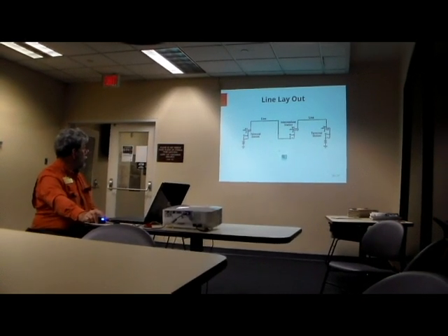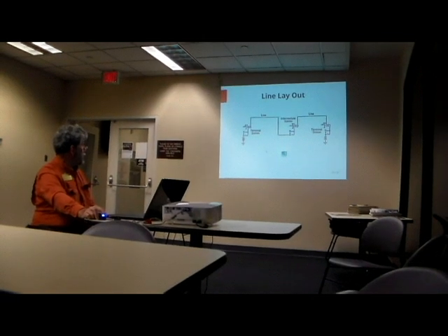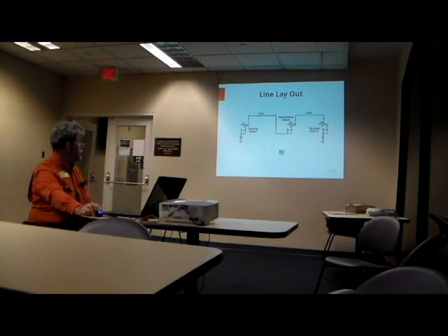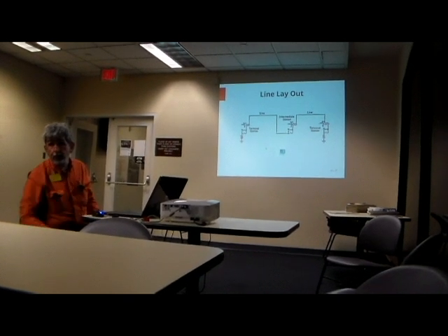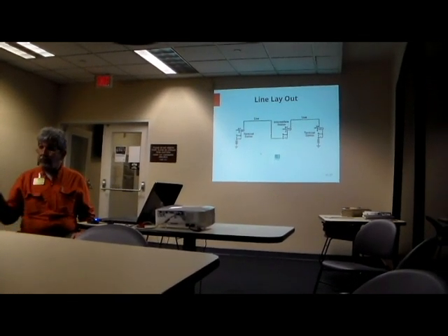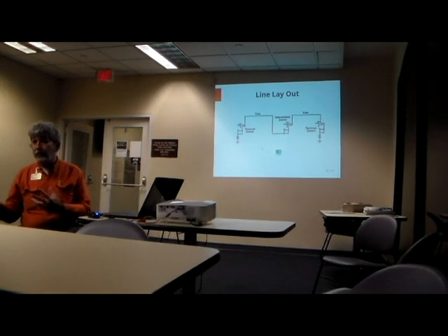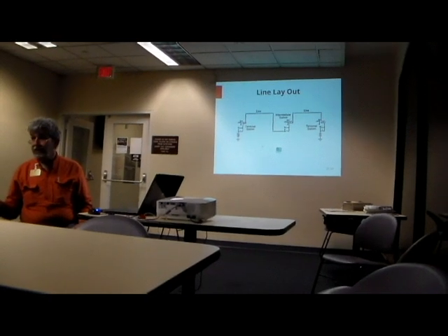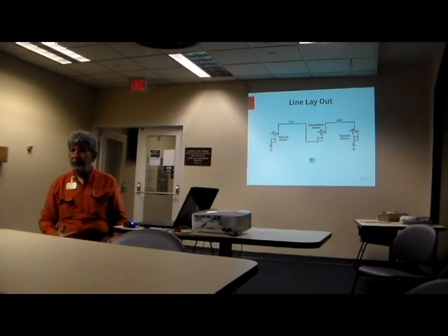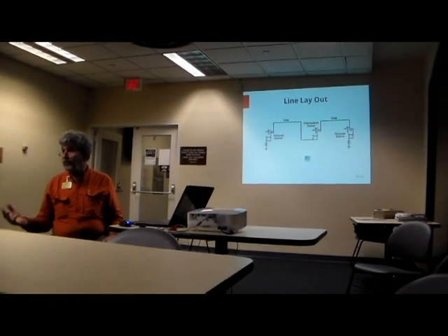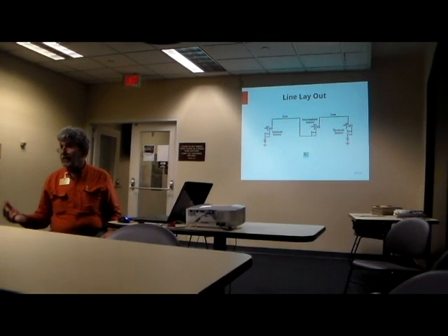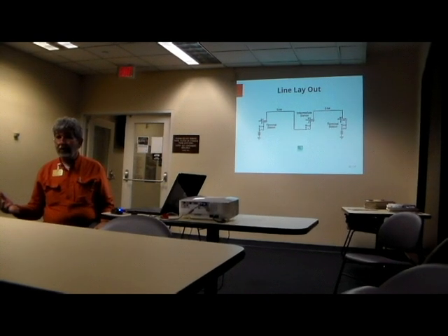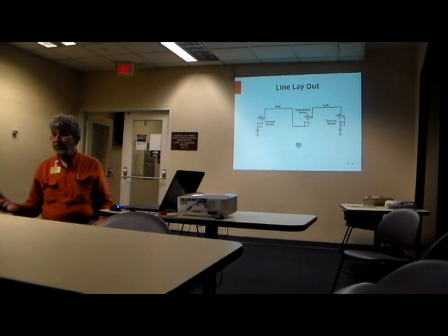Now, line layout. All we're showing here is the circuit closers, the key, and the coils of the relay. Unless you were right on top of the relay or it was a box or snare drum relay that I referred to earlier, you were going to have a heck of a time copying off of this. The terminals of the relay, the dry terminals, would control the actual sounder you'd copy from. And that nice hard click produced by that 1/4 amp flowing in the sounder was what was convenient to copy.